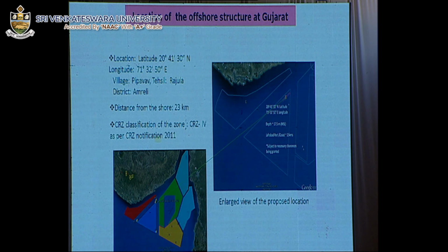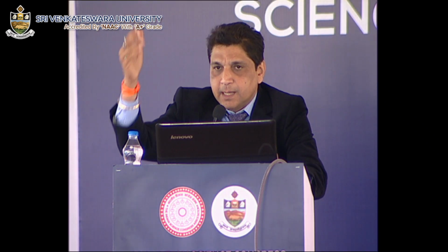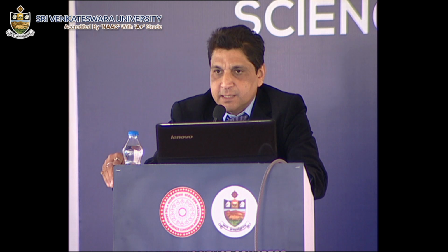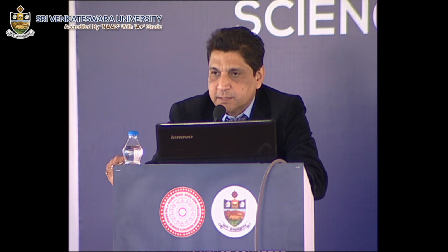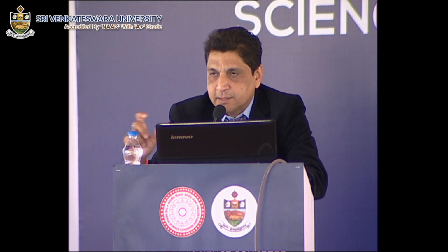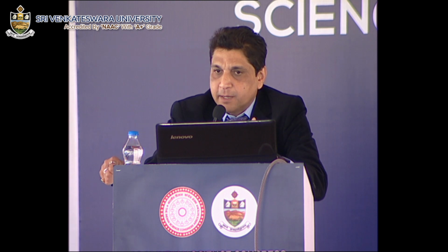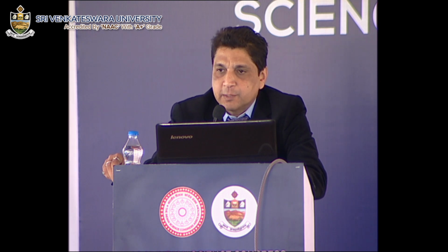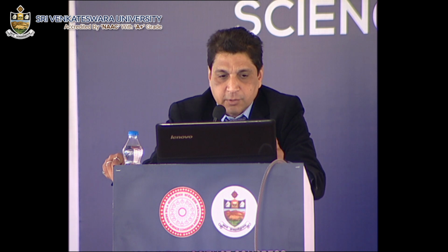What we mean is that light rays are emitted vertically upward to a distance of about 1 kilometer or 1,000 meters, and wherever there is a change in humidity or pressure variation, the rays come back. Using the time taken by the light rays to go up and come back, and the Doppler effect, we measure the frequency shift and then correlate the wind speeds as well as the wind directions for that particular area.